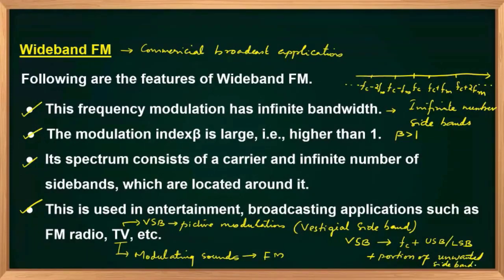That means it consists of carrier, one full sideband. Bandwidth formula for wideband FM we will discuss. I will give you the expression for bandwidth after FM, because both PM and wideband FM have the same expression for bandwidth. So we'll discuss that after discussing PM.